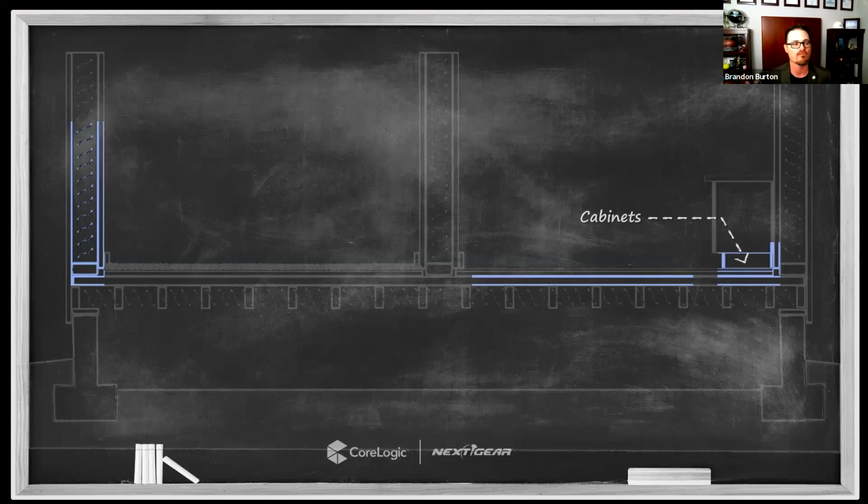These are all spaces that a general air mover is not going to address, right? That one for every 50 to 70 square feet, that one per room, that one for every offset for upper walls and ceilings, those are not addressing these spaces. So the use of air movement in these is above and beyond those calculations. So these spaces, if they are wet, I'd highly encourage that you have good documentation showing that they're wet. And then secondarily, we need to assess what is the most economical way to move air through this space, right?